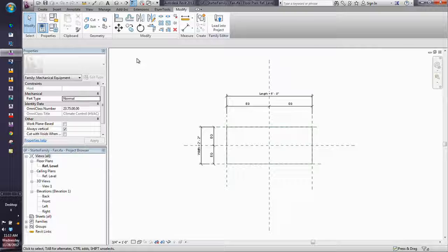So what you can do is actually move that connector. And this is where Autodesk said that was a problem. Because what happens when you take a pipe and stick it inside of the fitting? It immediately tries to do hidden line graphics for that pipe inside the fitting. So we actually cheated and borrowed something from AutoCAD MEP.